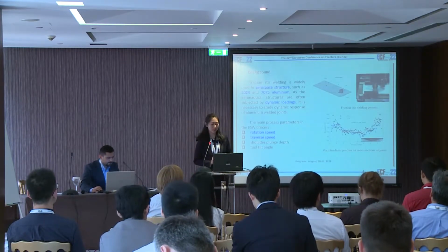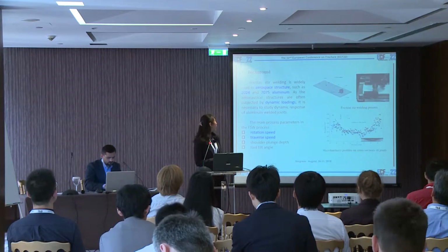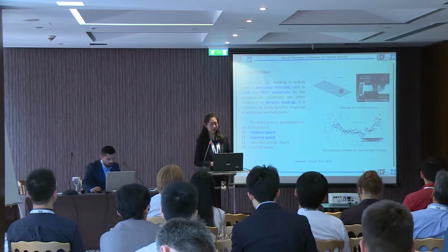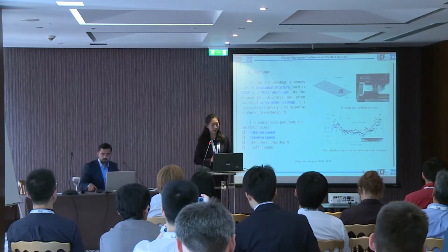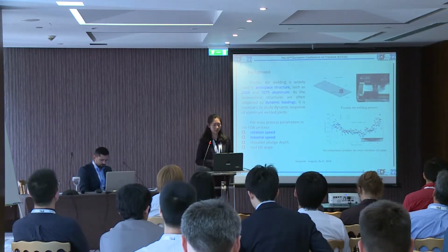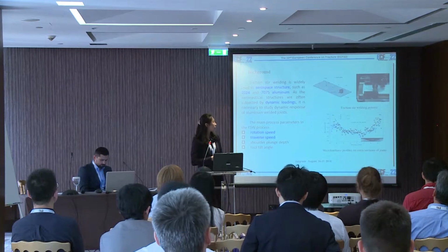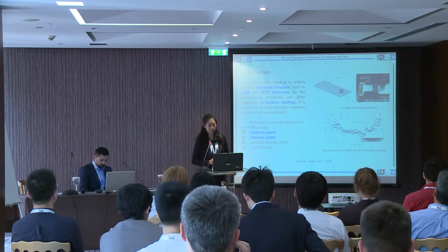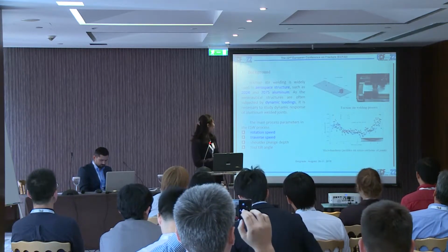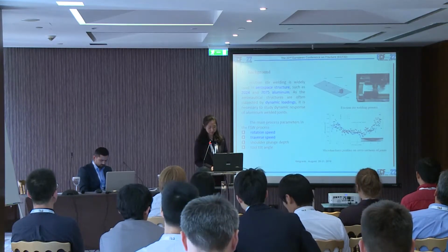Friction stir welding is widely used in aerospace structures, such as 2024 and 7075, which are very hard to connect by the conventional fusion welding method. As aeronautical structures are often subjected to dynamic loadings, it is necessary to study the dynamic response of aluminum welded joints. The former study of our group has shown that different welding parameters, such as the rotation speed and the transfer speed, have a big influence on the mechanical properties and micro-hardness of the welded joints.